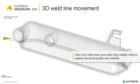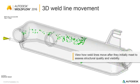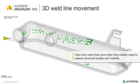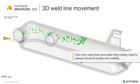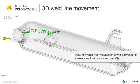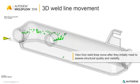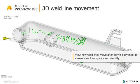But a very significant part of the material will actually streak away, and the material that was initially forming the weld line will have moved into other parts of the cavity. So what you can conclude from this is that this area probably had significant underflow, so that weld line is probably going to be pretty good.